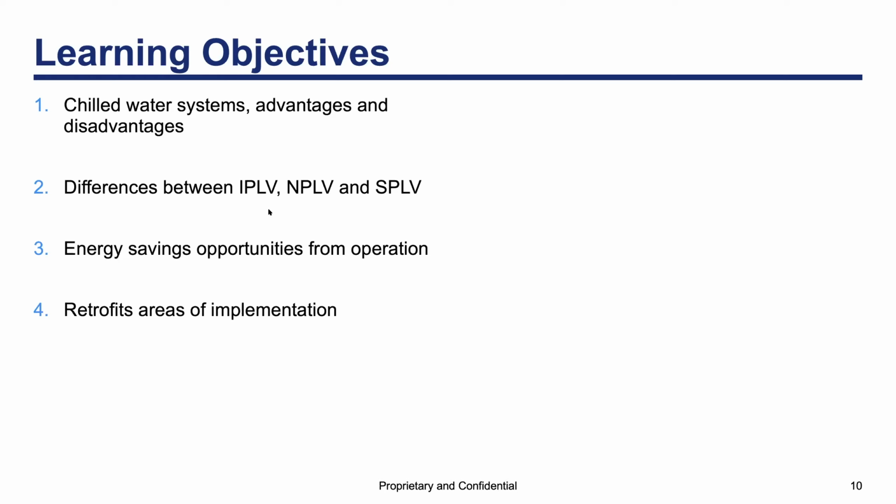The first point, we're going to review the main chilled water systems that we usually encounter in the field, and we will highlight the main differences between them. Then we are going to spend time reviewing some energy efficiency indicators, which simply put are single numbers that are calculated following a specific method described in the Air Conditioning, Heating, and Refrigeration Institute Standard 550 and 590. And this is important in this discussion, just to remind ourselves that we have different ways to calculate efficiency values, but one calculation in specific is about the system efficiency.